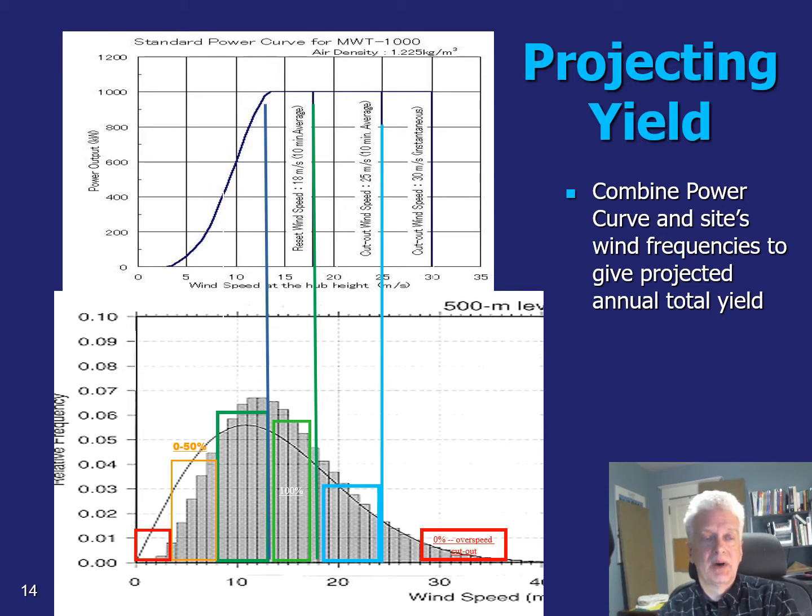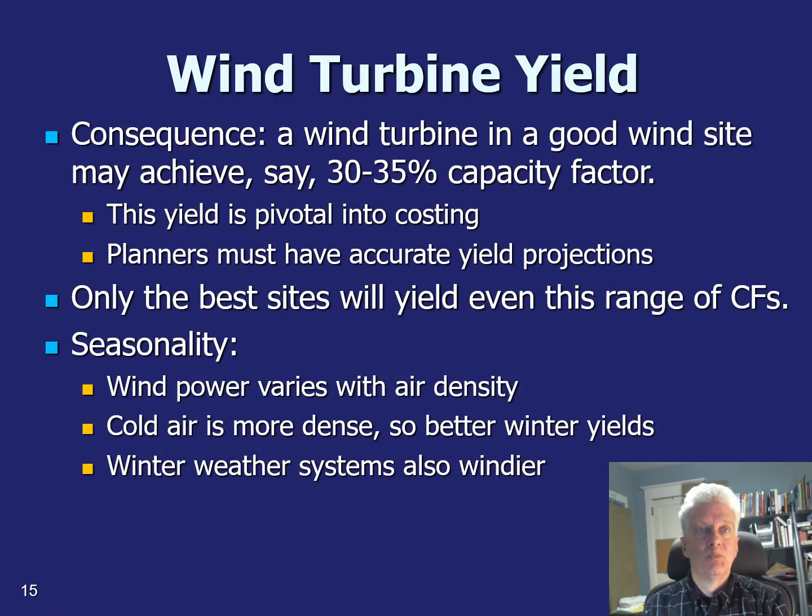And the bins inside the blue box, the pale blue on the right at 20 meters and up, those ones would only be available to you if the system has been able to get back to reset. So this statistical distribution doesn't tell you when these occurred, because it's time independent. You'd need to look a little closer if you expected to have it getting to the cutoff frequency once in a while. You could need to factor in that some of those blue ones wouldn't necessarily pay for you because the system had been in cutoff, had to wait for the wind to drop below 18 to let it cut back in again.